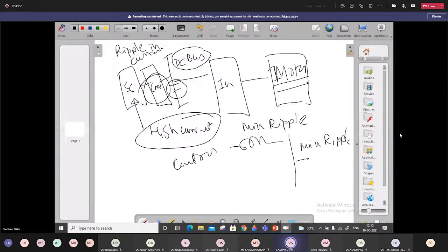Otherwise, the inverter control becomes very difficult if we are not able to keep the DC bus voltage constant. Then you have to implement a different strategy to operate your inverter with variable voltage. That is the reason why we use this converter, so that it can balance this out. And for other related issues, you might be very much familiar with the motor functionality, isn't it?